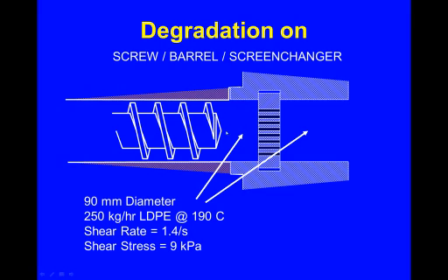And they don't accommodate for the length of the screw, and so they have a large empty area in here, and they want to make it easy to pull the screw if they ever need to pull the screw, so they don't have a reduction in volume here. And so if they wanted to pull the screw, they just index without a breaker plate in there, and then they can pull the screw right through the screen changer.